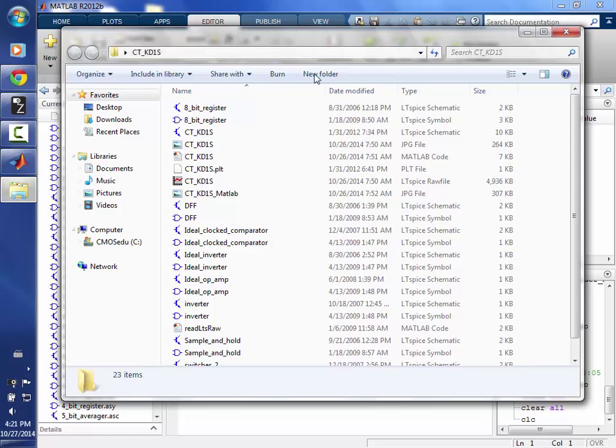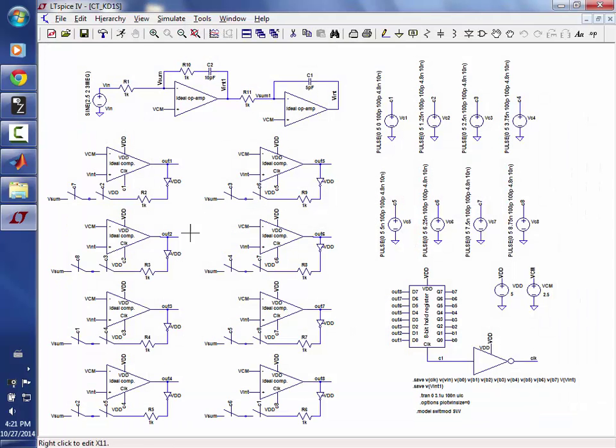Well, you know what, we actually need to look at the schematic. So this is basically the same thing as the other topology, except in our feedback path we have a resistor. These switches here aren't for switched capacitors. Both switches have to be on in order for the resistor to be connected back to the integrator.